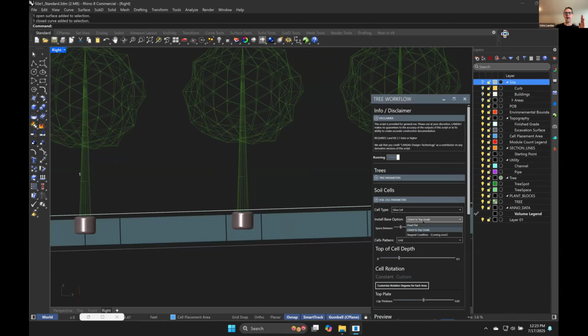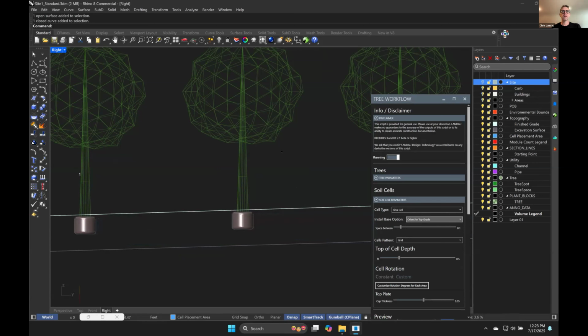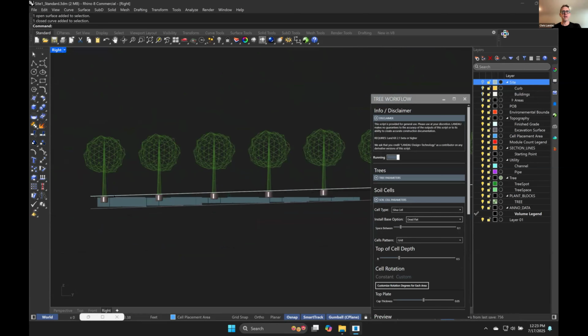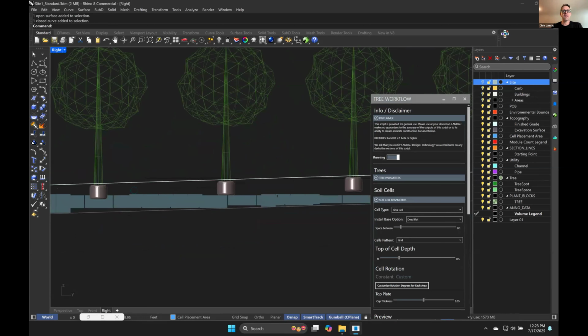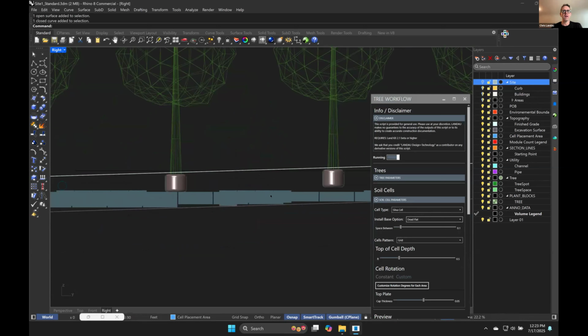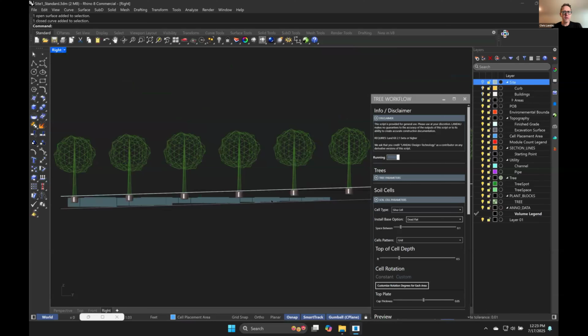And if we change this to dead flat, it's a great option, but not for this sloping street, right? For the sloping street that's at whatever 5%, if we made it dead flat, here's what we would get. Let me zoom out here. It's gonna look for the lowest grade, and then it needs to find one singular dead flat location, and then it starts there and it builds that. And that's it. I think the ones we're seeing that are a little higher are across the street, possibly on the other side of the street. So that's a challenge there.